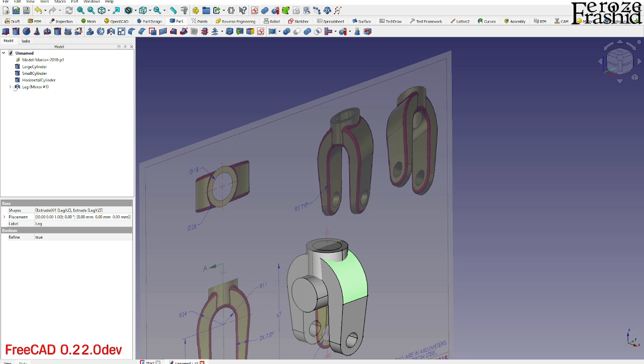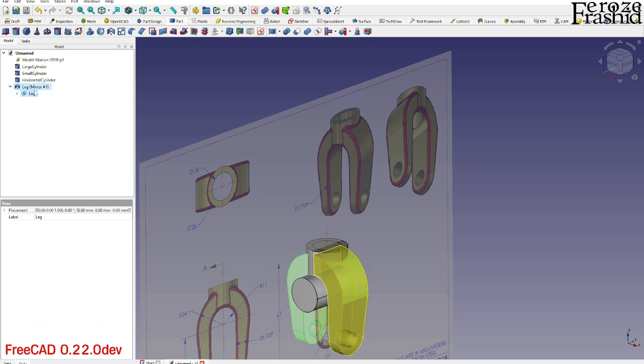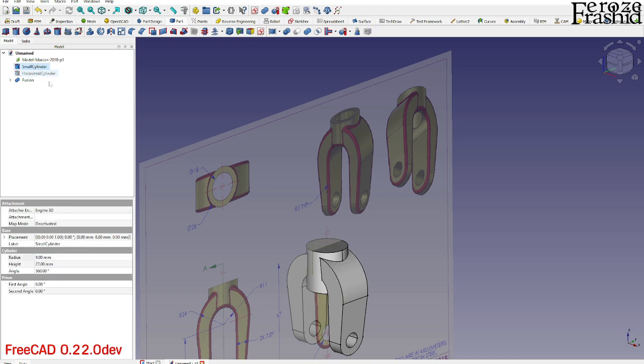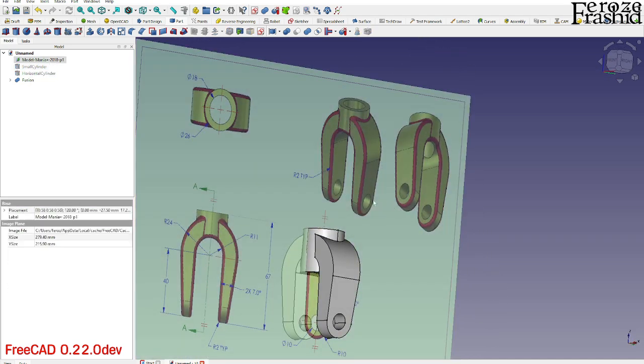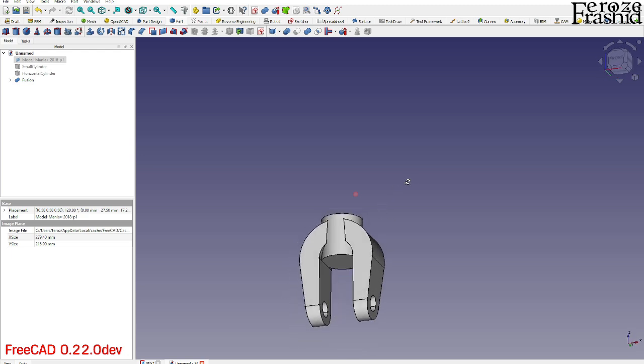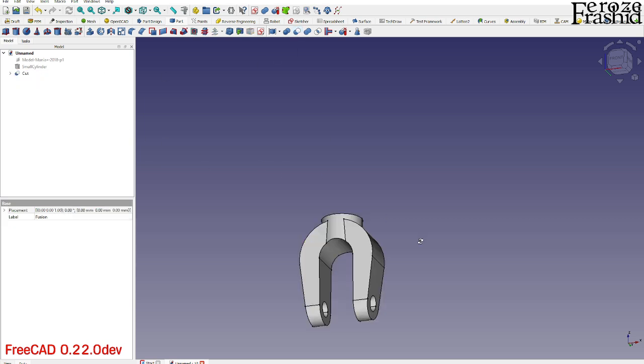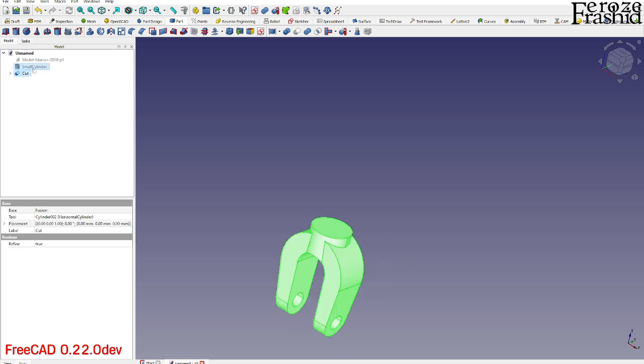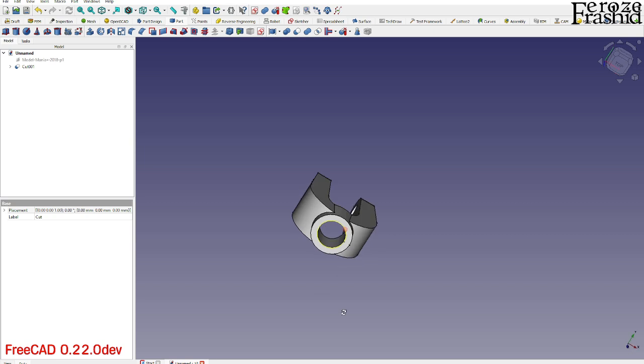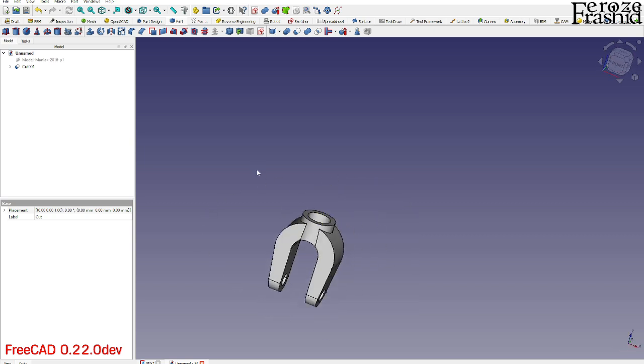Now on here, I want to make these two one fusion. As usual, after every time I mirror it, I place them as a fusion. Now this time I can pick on the large cylinder and make all of them as a fusion. Okay, without these two cylinders, we have this. Now I want to cut away this mid part. So take this and take the horizontal cylinder and make a cut. And finally, take the small cylinder away, and there it is, our phase 1.